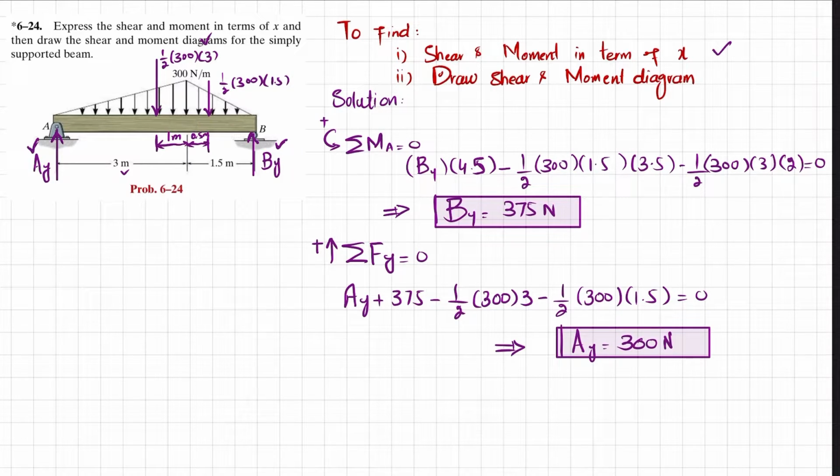So what we will do is cut this beam. I will choose another color. You can cut this beam over x greater than or equal to 0 and less than or equal to 3, till this. Clear? And when you cut it, you have to draw the shear force and bending moment diagram.